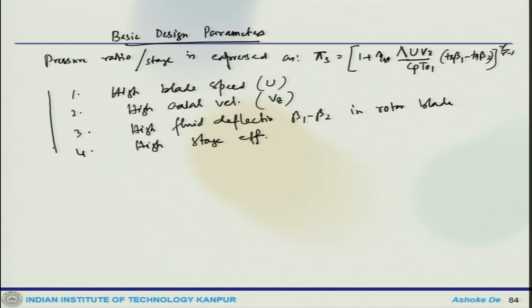see when you increase the rotational speed, obviously there is a limit to what one can do, because there is a structural load, or the stresses would increase on the rotor hub. So, further increase in the rotational or the axial velocities, that means u and v z, is also limited by the tip Mach number.